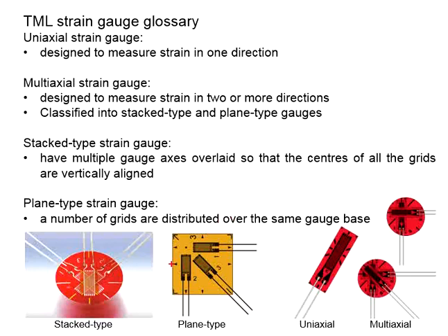To determine the exact locations, you will need to refer to the measurement axis for every single strain gauge. These are the measurement axes for this strain gauge. This is meant for this strain gauge, and this is meant for this strain gauge. As for the staggered type strain gauge, the measurement axis will be something like this.